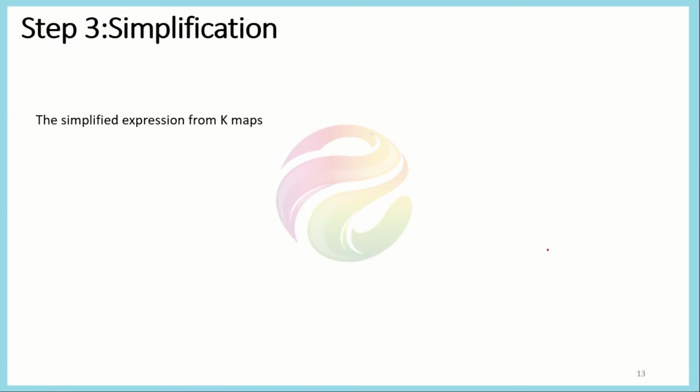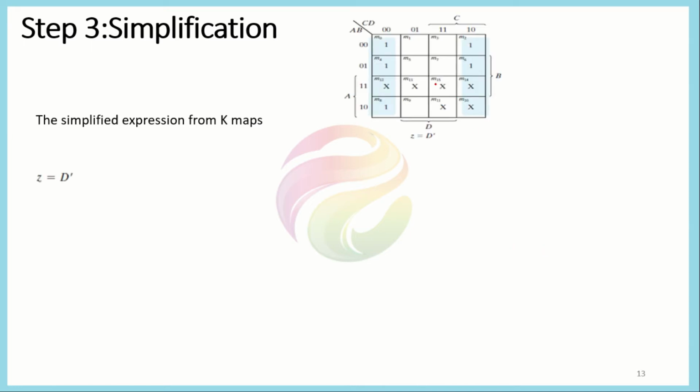This can be expressed by considering all the min terms and checking on which values we have Z equal to 1, and that would represent the min terms for this function Z only. If you see the truth table which we discussed in the 2 slides below, we have 1 here at M0, M1, M4, M6, M8.